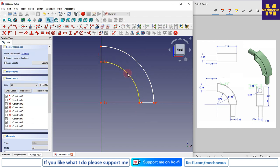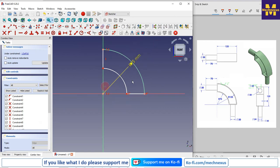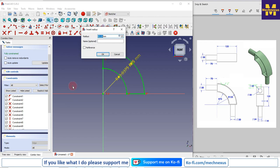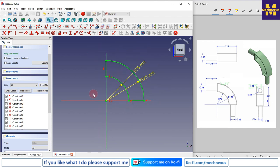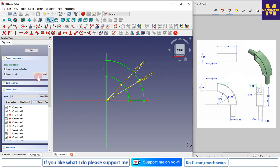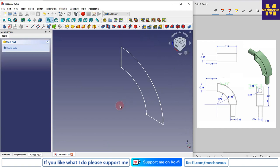Now we will give the dimensions. So this one is R75 and the outer one is 125, so I will give the 125 and I will move my dimension so that it is clearly visible. And now our sketch is fully constrained, so I will come out of the sketch and press 0 to go to the isometric view, and now I will extrude it.